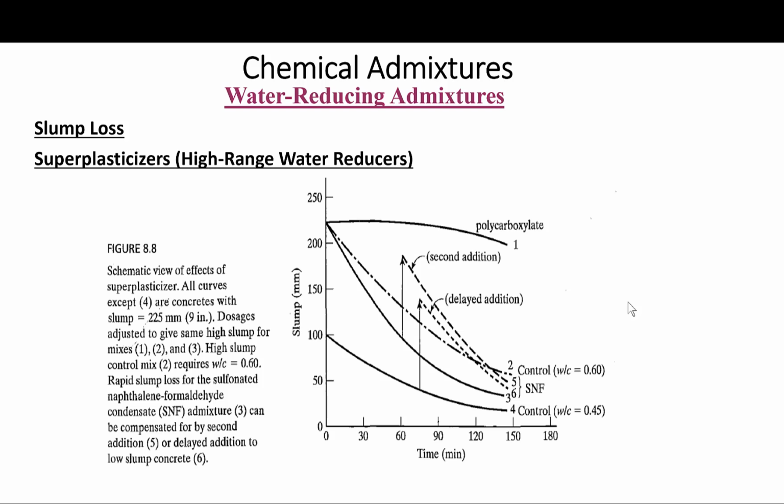Also, you need to remember, sometimes admixtures that also have retardant tendencies can cause workability problems, basically due to acceleration of the early hydration of C3A. So in extreme cases, flash set can occur. Delaying the addition of the admixture will often alleviate this problem, or maybe an alternate admixture can be used.